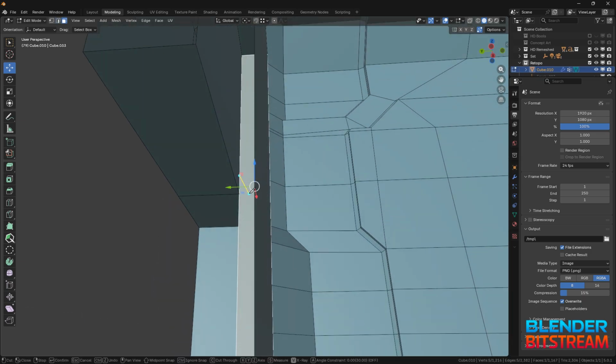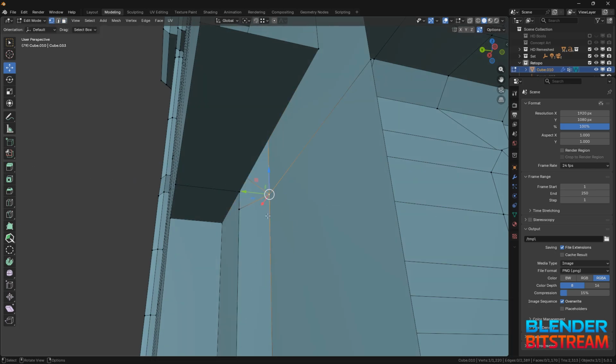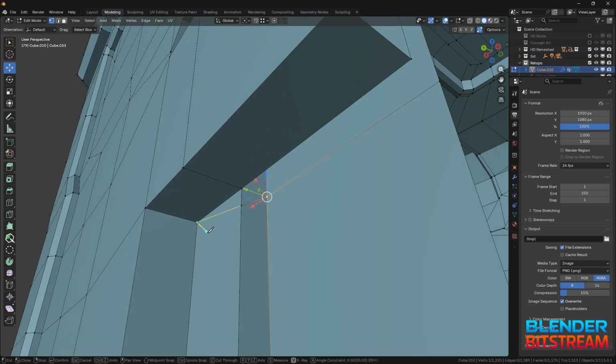Here I'm using a cut tool technique to get 5-point vertexes around this double corner. This is a common issue, and this cut solution will serve you well in retopology.